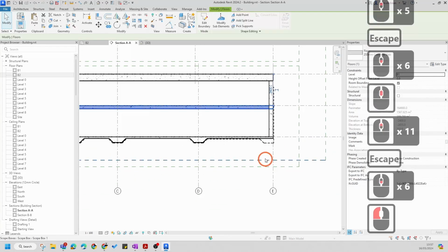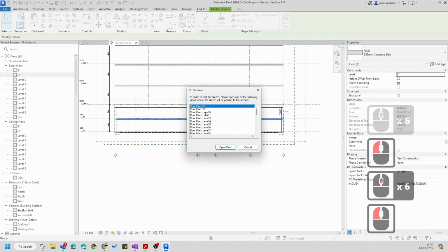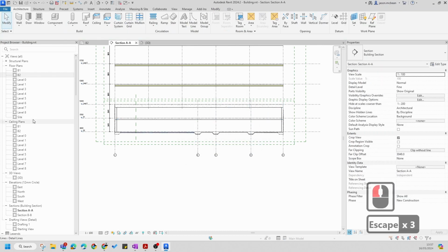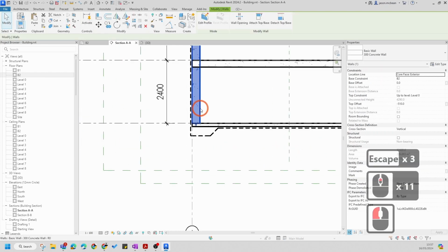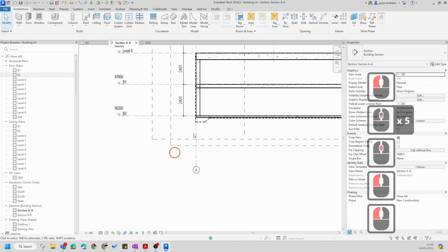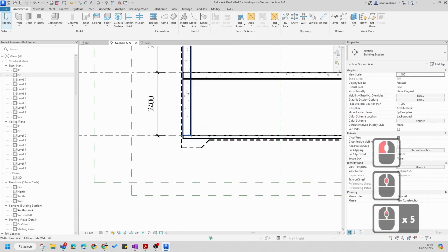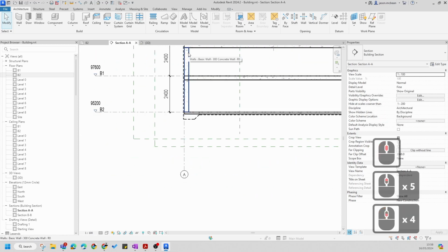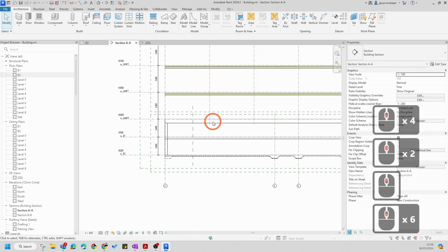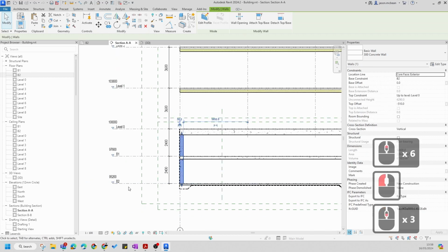Okay, now we've noticed that this floor slab, if I go and edit this boundary, and please note that I've drawn the wall from basement 2 to level 0, because in essence that's how it's going to function. So you won't have to draw a wall up to there and copy up another wall. Okay, there are circumstances when the interior walls that you use that approach, but in essence I know that this concrete wall is going to go from B2 to level 0.